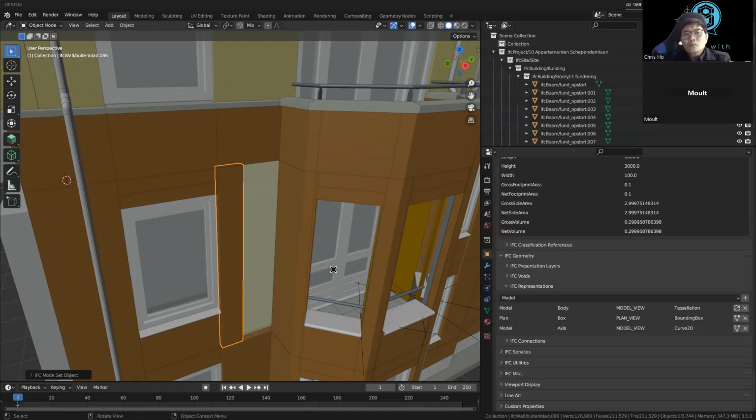If they have used an incorrect geometry type, you may need to convert from one geometry type to another. You might need to convert an extrusion to a mesh type of geometry, or vice versa. For example, if you have a whole bunch of structural steel beams, which are best described as extrusions, because that's how beams work, that's how they're manufactured, that's how they're installed. But if they're described as a mesh, you may want to convert them into parametric extrusions so that you can easily edit things like their web thickness or their flange thickness and so on.